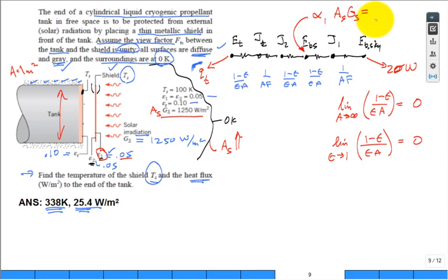All right, so this is coming in. Let's go back here. Do I have enough information to get the EB of the tank? This is equal to sigma temperature of the tank to the 4th power. The temperature of the tank is 100 Kelvin. I can calculate that.